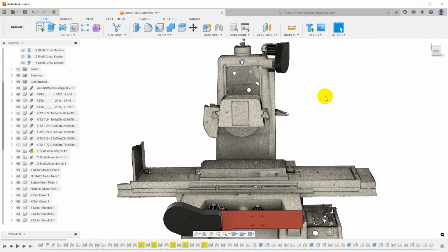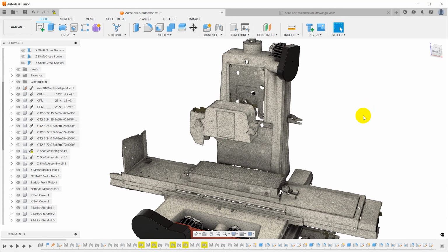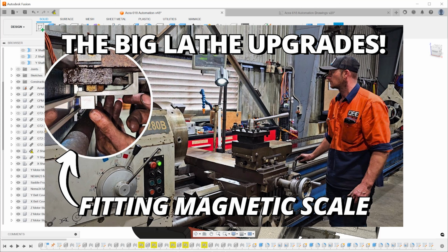Now, different people do call these axes differently. You see this most often on a lathe. On a lathe, technically, the long axis along the bed of the lathe is parallel to the spindle. So that should be called Z. However, if you go out and look at lathe DROs that you can buy, sometimes it's labeled Z, sometimes it's labeled X.